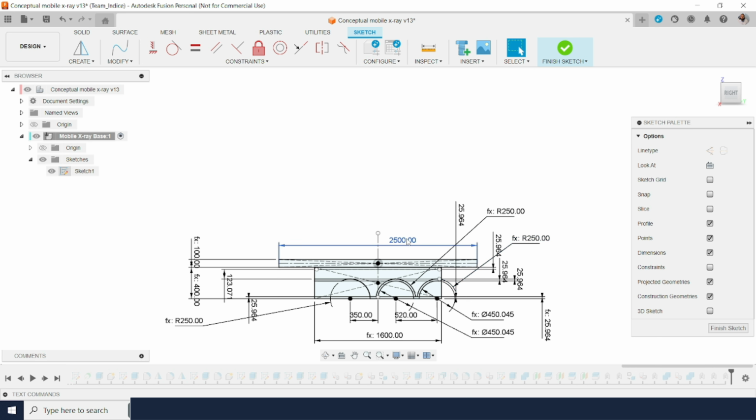If I click on this, this is my dimension 1. As you can see, this is the dimension d1. This is the length of the component, and if I go to the width of the component, I have also used a formula. So this is basically d2. D2 is d1 divided by 25. Basically, I have reused the dimension value of the length for the dimension value of the width. Similarly, I have used other dimensions as well.